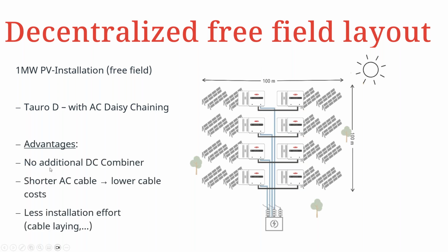Of course, the advantage comes as on the previous occasion, no additional DC combiner boxes. But then most importantly, you have shorter AC cable runs, which of course implies a lower cable cost.